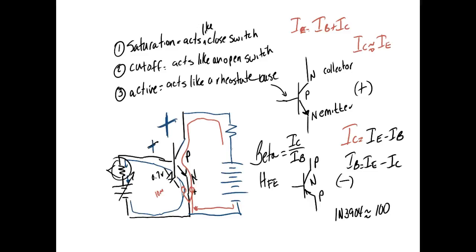Because if you ever got it to 0, you'd burn your transistor up. So it'd be easier to put a fixed resistor there, so you know you always got R no matter where the power supply is set. This makes it a little hard to do on our trainers because our trainers are set up like this. It's got 2 power supplies in there, and that right there is common.